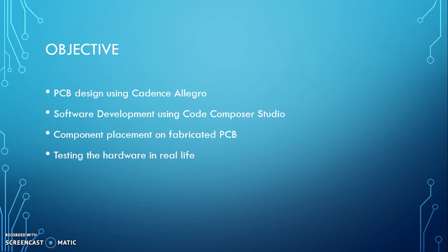For that purpose, I designed a PCB using Cadence Allegro PCB editor, and I developed the software for the microcontroller, which is MSP430F2232. I soldered the components on fabricated PCB and I tested the hardware in real-life situation.